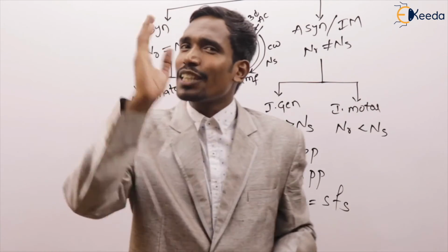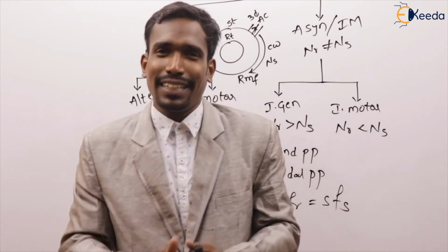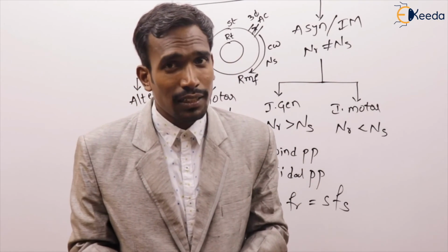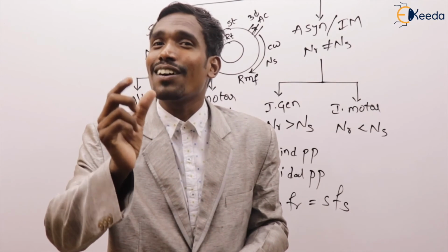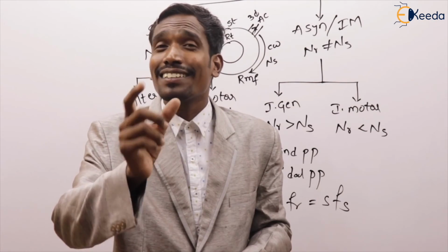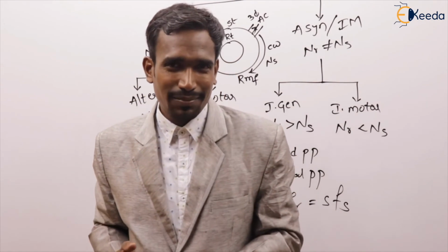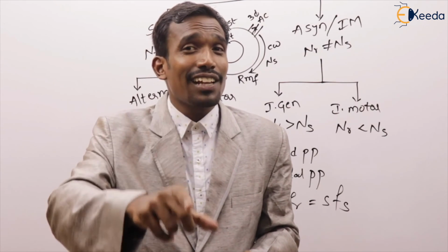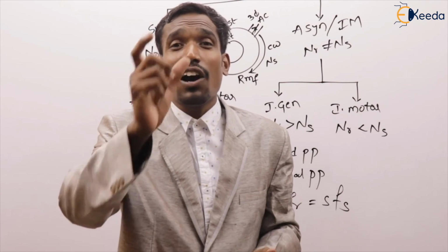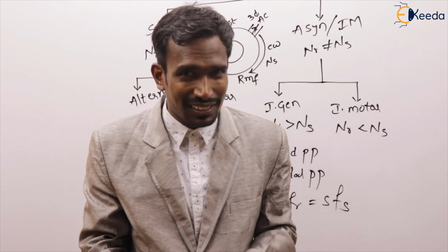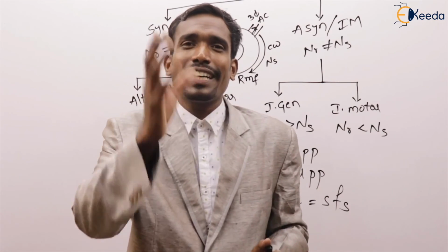Exactly, the transformer has higher efficiency than the induction machine for the same rating. Sir, why? The friction and windage losses are 0 for the transformer, but these are not 0 for rotating machines like our induction machine.